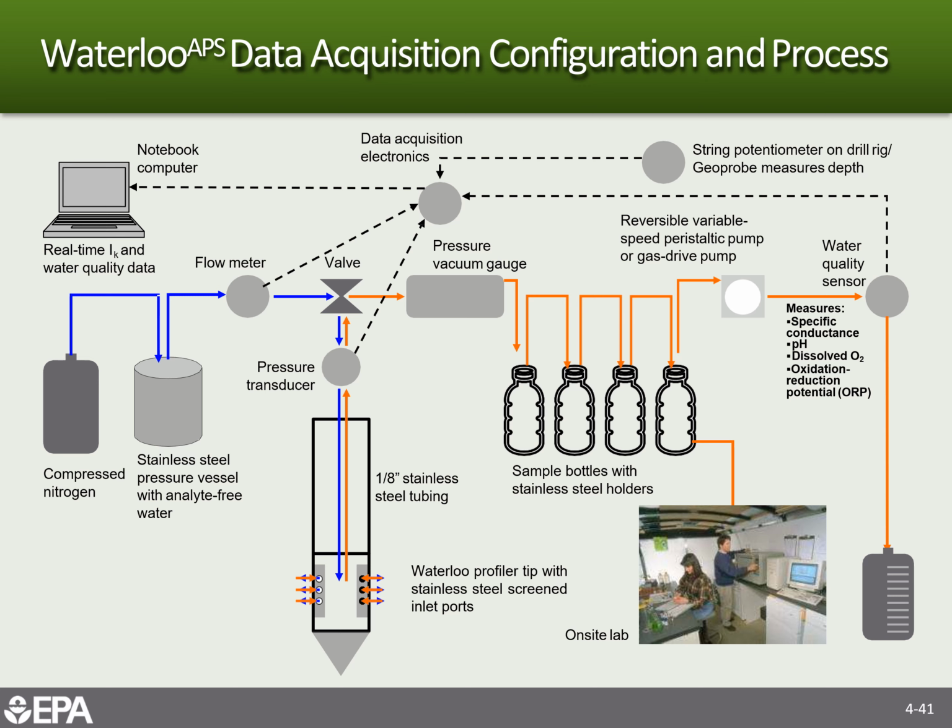And you can then, I think, do these field parameters, which are often so very important to understanding the characteristics of your aquifer. Is it low dissolved oxygen? Is it a negative oxidation reduction potential? All this is really important for understanding your aquifer characteristics and the state of your contamination. And then you can use the water samples that are collected with their on-site lab.